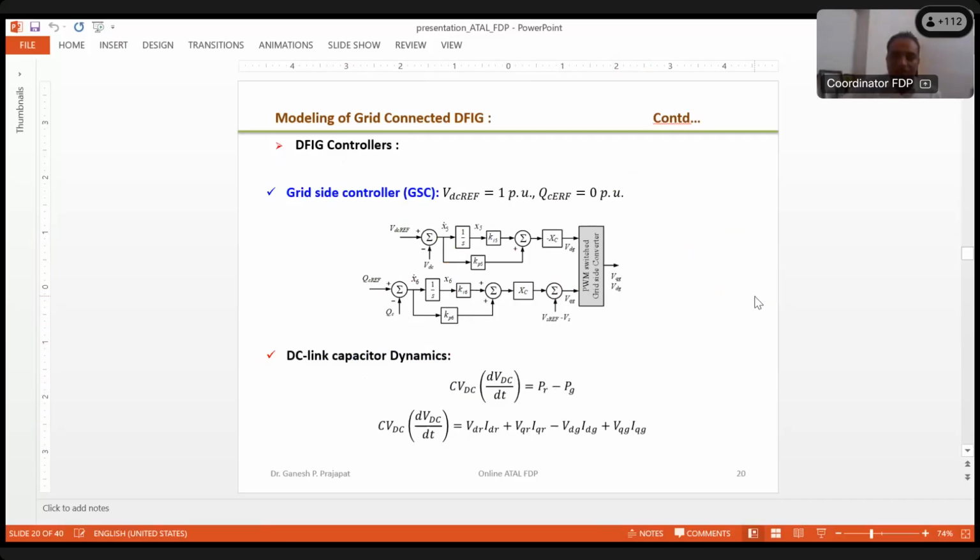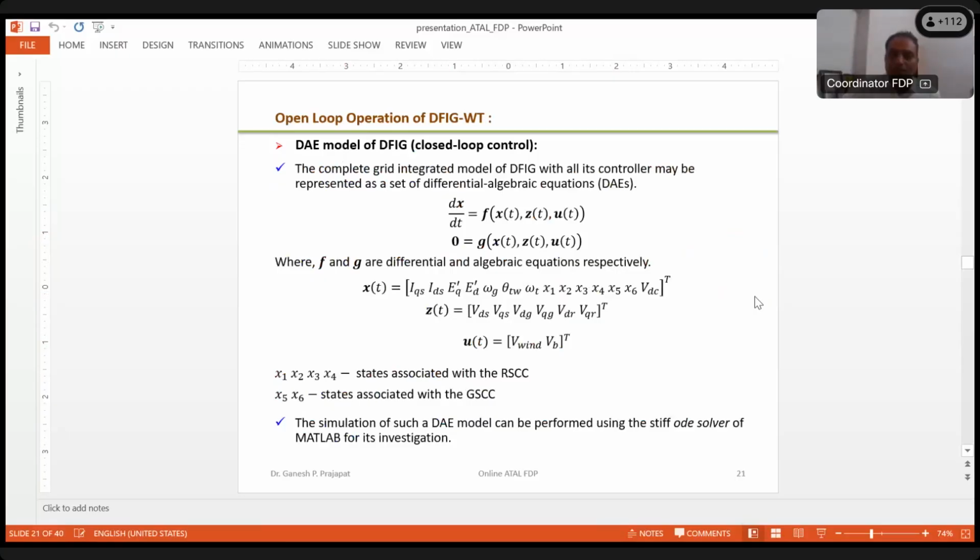By associating all these equations, again we are doing the model analysis, now with the controllers. People from electronics or electrical engineering know that whenever we put in one PI controller, it always adds one more state. A state is just a variable which gives the internal characteristics of a system. Any mechanical dynamics which is rotating or has some rotating part always has states which give information about the internal parts of that system. That is basically known as a state.